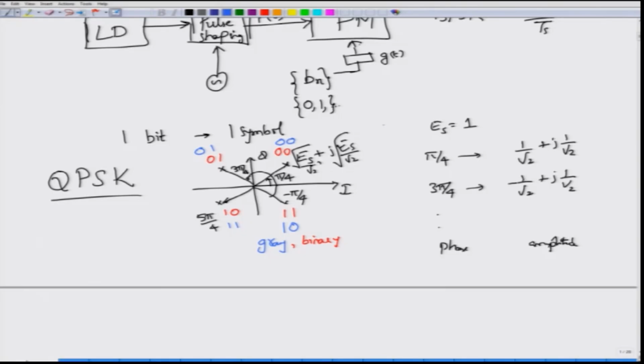So, what you have done is you had these bits with you, and the group of bits which form a symbol. Bits or symbol, both of them are equivalent, and that has been mapped onto the phase. The phase has been given by a certain value of the signal that is being carried. So, you take the bits, group them into symbols, and then map these symbols onto the corresponding phase of the carrier. In general, for a QPSK signal you can write the expression as the ith waveform. There are 4 waveforms obviously.